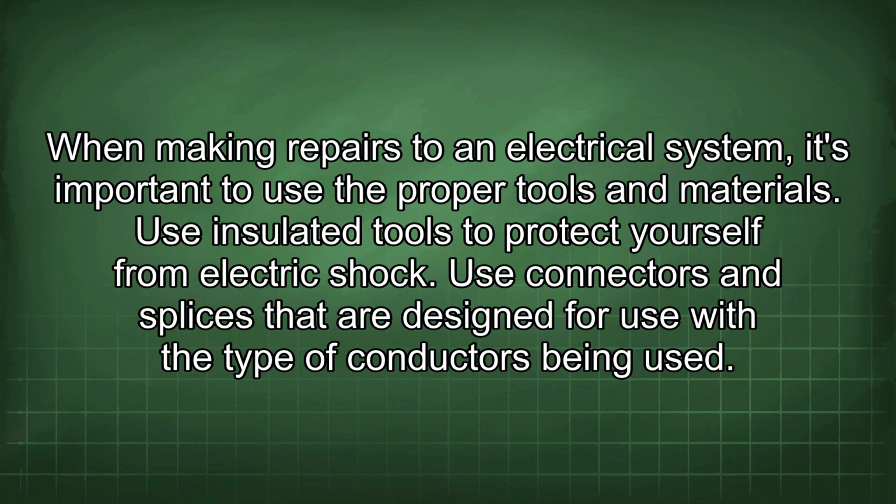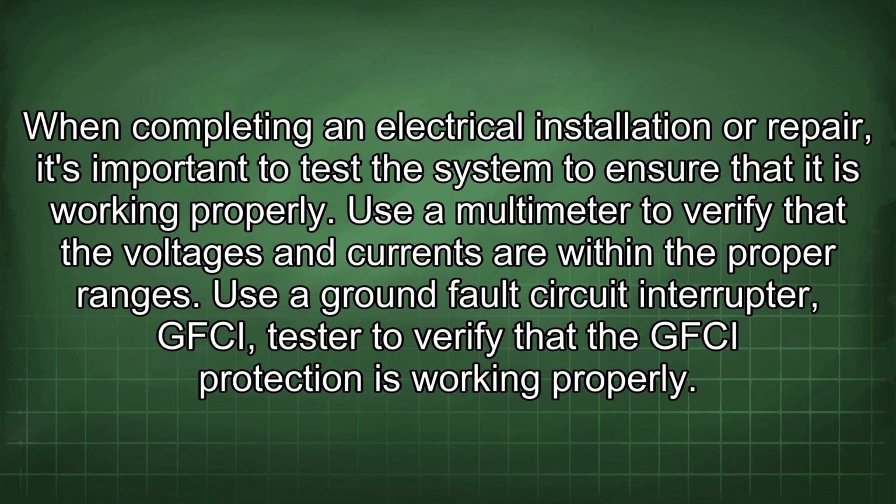Use insulated tools to protect yourself from electric shock. Use connectors and splices that are designed for use with the type of conductors being used. When completing an electrical installation or repair, it's important to test the system to ensure that it is working properly.